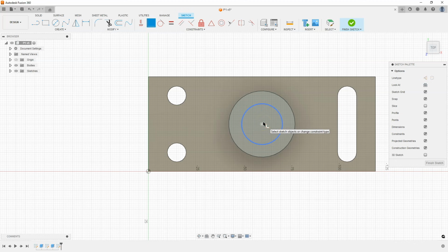In both cases, using automatic constraints and adding constraints manually, we get the same effect, and we can think about which way is better. Automatic constraints have the advantage that you don't have to perform additional steps, you don't have to select a specific command, and you limit the number of clicks. This will usually be a faster way. However, there may be a situation in which it is difficult to use automatic constraints, and the constraints added manually, even though additional steps will be required, will be much faster, and more importantly, they will make us sure that we have used the exact constraint that was necessary.